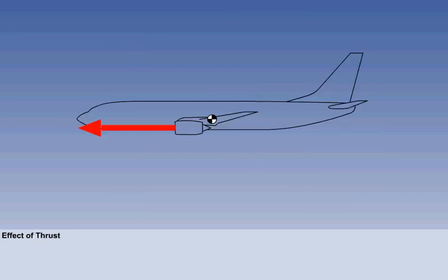The effect of thrust on longitudinal static stability will be greatest at low indicated airspeed and high thrust, such as during takeoff and the approach to landing. The vertical location of the thrust line defines one of the contributions. The illustration shows an aircraft with pod-mounted engines beneath the wing.